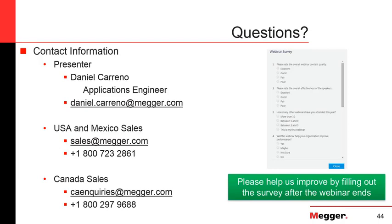But no, you don't need that, because you face, let's say, very different transformers, and you will be able to measure those with the same instrument. So no, the rated voltage of the transformer doesn't come into the picture when choosing an instrument for low resistance or for winding resistance testing.